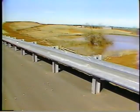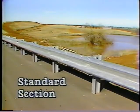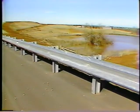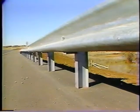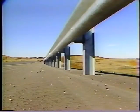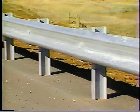The standard section of a strong post system is usually not hit head-on. It's normally hit at an angle and must be strong enough to deflect the vehicle and redirect it away from hazardous conditions. The effectiveness of the standard sections in a barrier system is influenced by the system's length, how the standard section is attached to the rest of the system, the height of the barrier, the roughness and slope of the terrain, and the rail tensile strength.